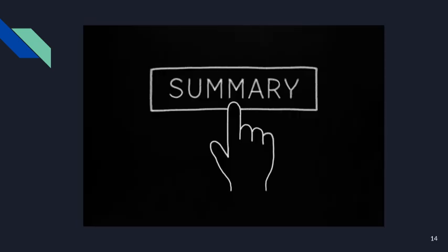This chapter has revealed some physical properties that are used in measurement sensors. The first principle covered was capacitance change, which we found was based on two capacitor plates with either a variable or fixed distance between them. We learned that sensors with a variable distance between the plates are primarily used for displacement measurement, either as displacement sensors in their own right or to measure the displacement within certain types of pressure, sound, and acceleration sensors. The alternative type of capacitive sensor, where the distance between the plates is fixed, is typically used to measure moisture content, humidity values, and liquid levels.